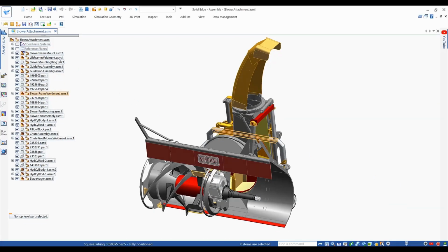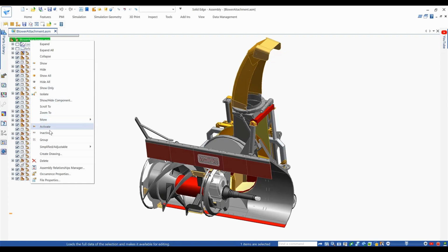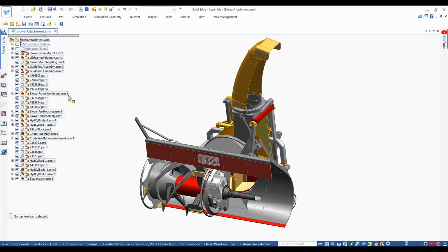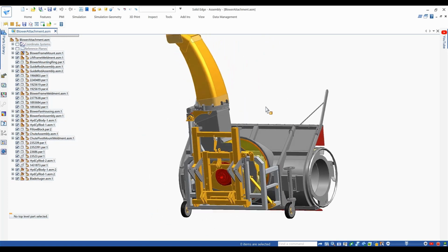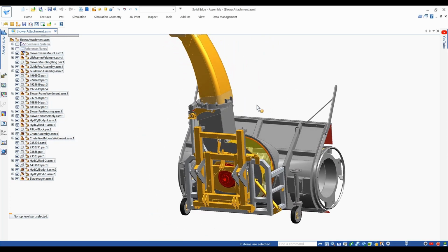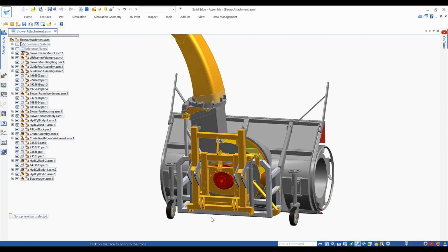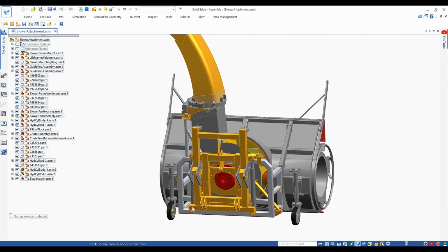First thing we'll do is inactivate all of the parts in the assembly. You'll notice that as we hover over the assembly, the individual parts are highlighting, even while inactive. Now, we just covered some of the supported workflows for inactive components, one of them being look at face. In the past, we had to activate the part before using this command. But now we simply run the command and click the face without activating.